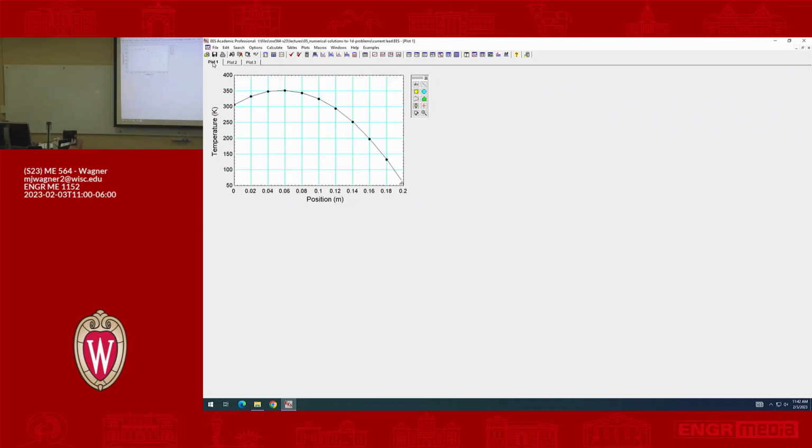I've actually done this already a little bit cleaner. So we have 11 nodes. I guess we're noticing something kind of interesting, right? That the temperature is going up before it goes down. I mean, there's thermal generation in the wire, so I guess that's possible, right? It's 1,000 amps we're trying to run through this thing. But yeah, this is a solution. I guess it makes sense. What we could do is then go back and do an analytical solution, if we were able to, and maybe make a comparison there. You'll have to do something like that in the homework. Any questions on this?